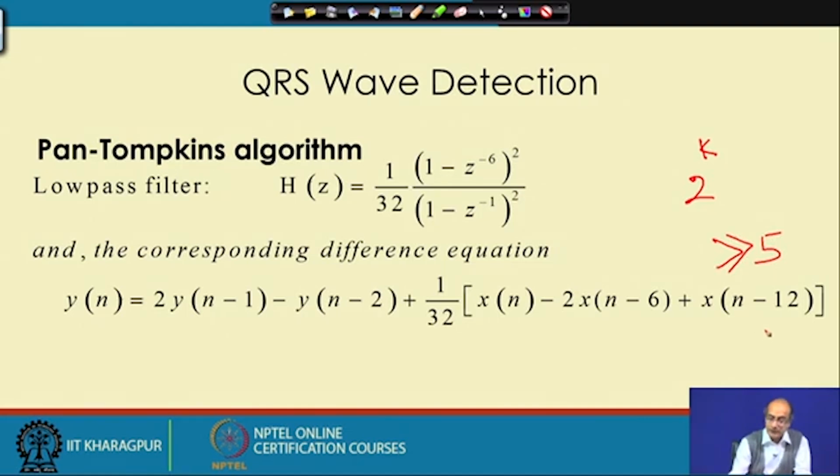Okay. So, keeping that in mind, when we are multiplying with a power of 2, that would be a left shift operation. One left shift operation will give us multiplication by 2. Here also we will do the same thing, and when we are dividing by 32, that would be effected by 5 right shift operations. Okay. So, that is the way they have implemented it, so that the operations can be done in a very fast and frugal manner.